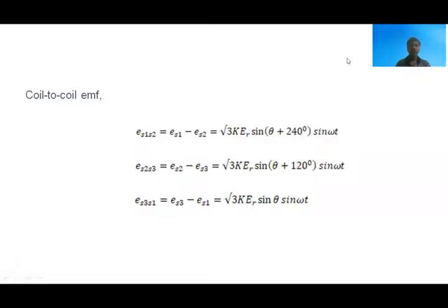Therefore, the mechanical rotation of the rotor is converted into the electrical voltages at the stator windings. These stator winding induced EMFs are transmitted to the synchro receiver or synchro control transformer to convert these voltages back to the mechanical rotation to drive the load connected to the motor.